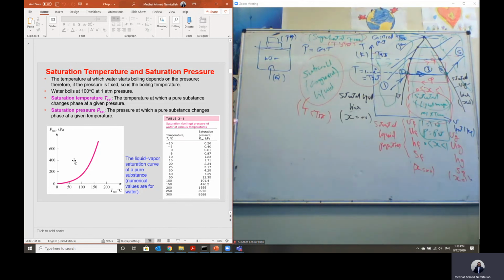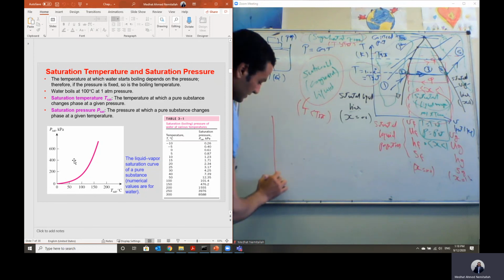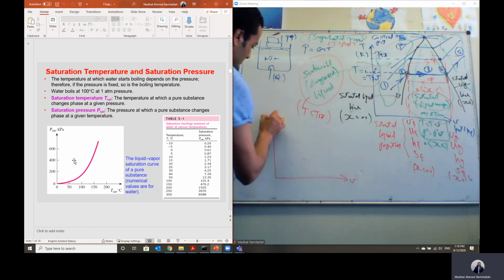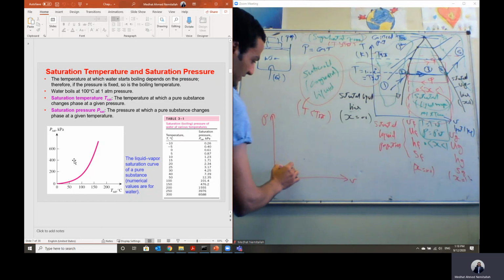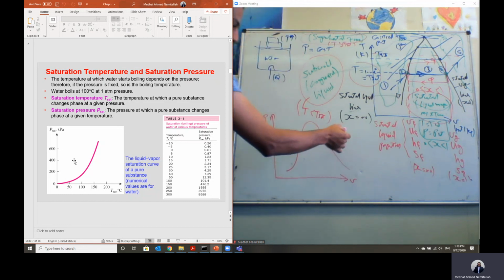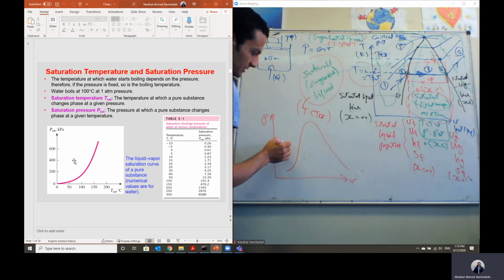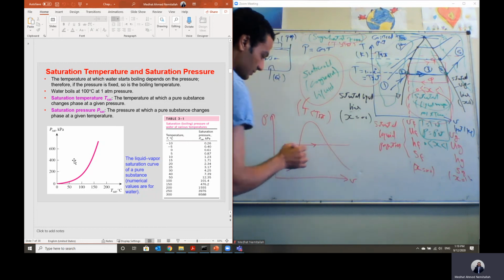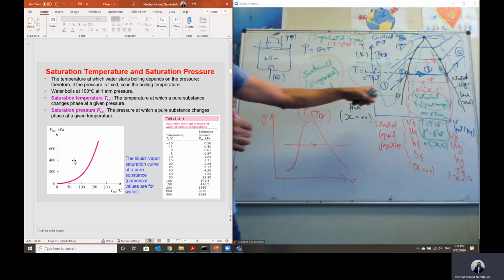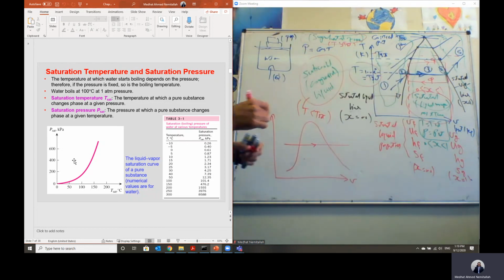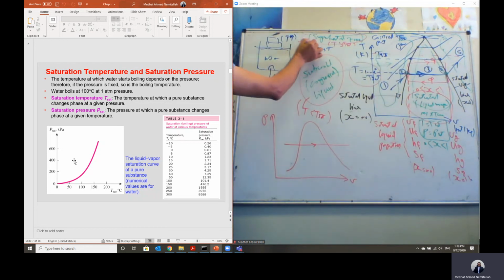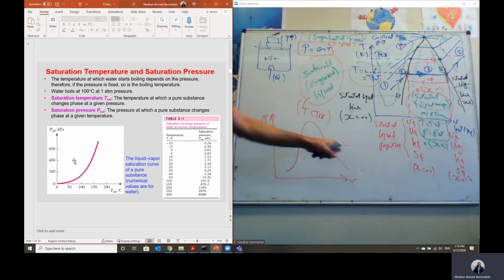Okay, we can also represent this process on the PV diagram. This is the TV diagram. On the PV diagram, it will be much simpler. We can get the same curve at different pressures. We can repeat the process, and you can get this saturation curve. On the PV diagram, points 1, 2, 3, 4, 5 are at the same pressure. This is the phase change process, and it is done under constant pressure. On the PV diagram, a line of constant pressure is just a horizontal line.